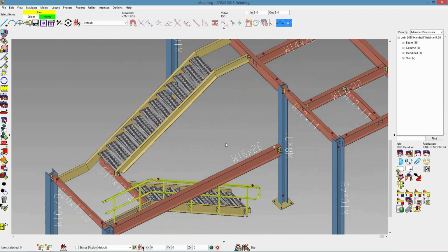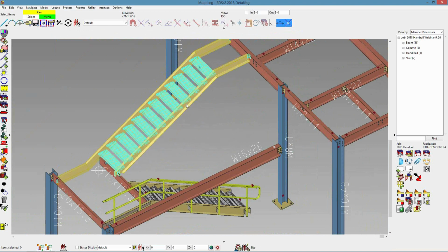Before, when you used to add a handrail to a stair stringer, you would have to surface to the top of the stringer and then create a section view. And then you would have to get to that elevation view, lay out some construction lines, and pick your points for how you wanted the handrail to be. Well, now I can just select the actual stringer I want to add it to. So you don't select the whole stair, you just select what stringer on that stair you want to add it to.